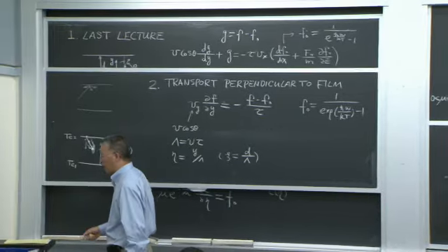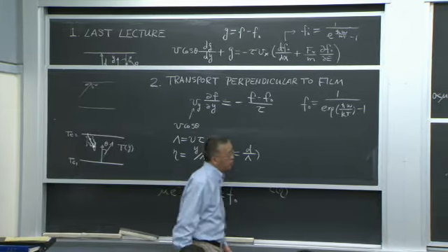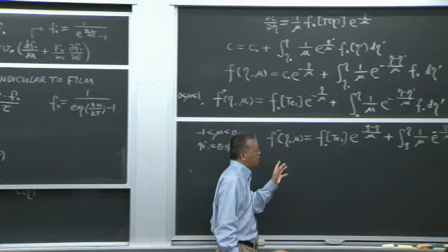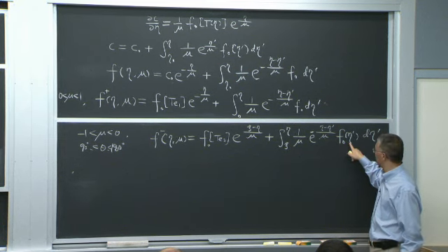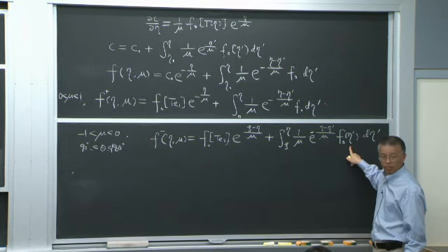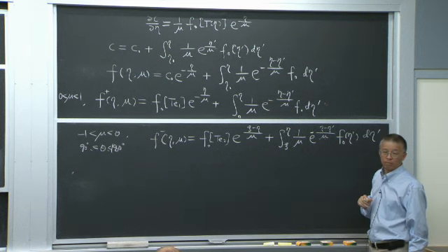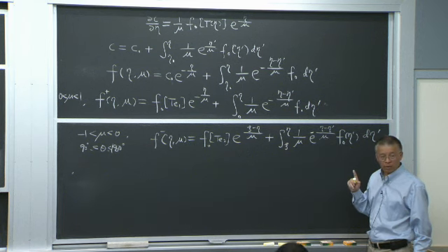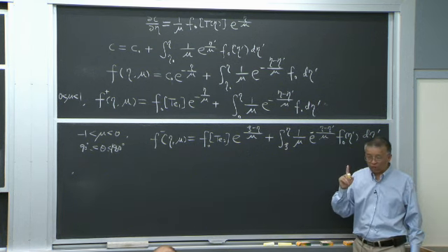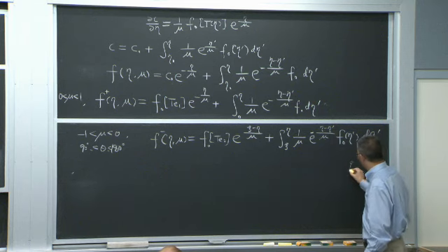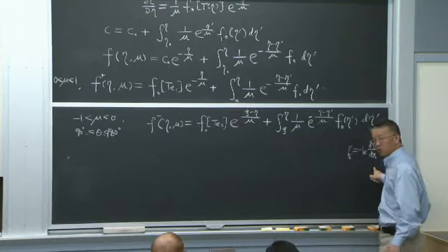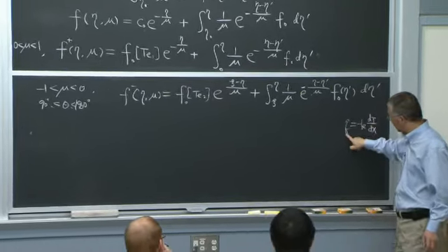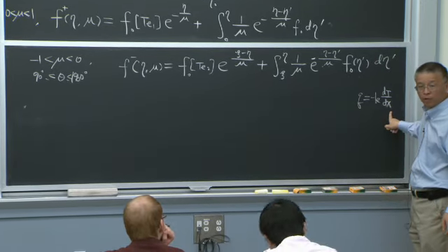So now I have the distribution function, and my challenge is, remember this one, F0, is a function of eta itself. I do not know it, right? It's inside the integral. And what I have is a non-local transport. It's not like Fourier's law of heat conduction where Q equals minus K dT/dx, right? That is a local transport, because the heat flux is proportional to the local gradient.